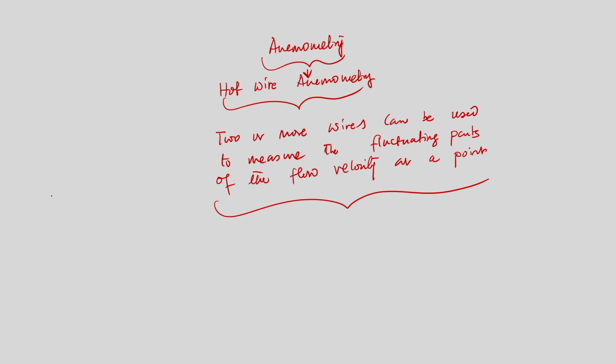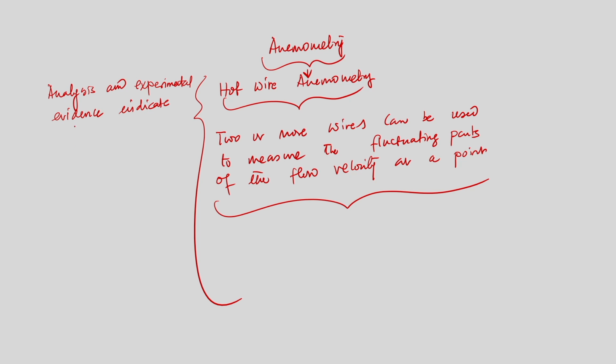If we recall that analysis and experiments, I can say experimental evidence indicate that the hot wire response is given by I square R heating, that is nothing but A plus B root u.